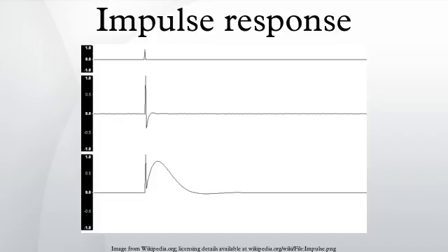In Fourier analysis theory, such an impulse comprises equal portions of all possible excitation frequencies, which makes it a convenient test probe. Any system in a large class known as linear, time-invariant is completely characterized by its impulse response. That is, for any input, the output can be calculated in terms of the input and the impulse response. The impulse response of a linear transformation is the image of Dirac's delta function under the transformation, analogous to the fundamental solution of a partial differential operator.